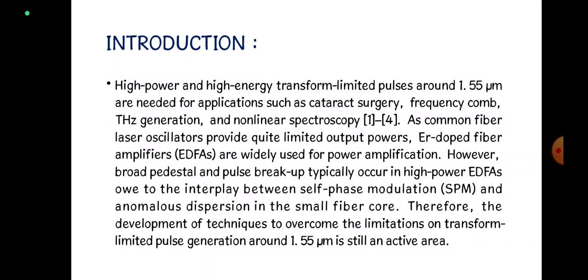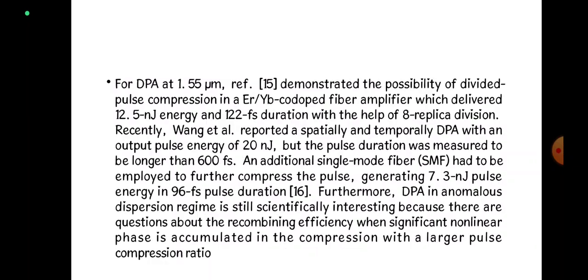However, broad pedestals and pulse breakup typically occur at high power, due to the interplay between self-phase modulation and anomalous dispersion in the small fiber core. Therefore, the development of techniques to overcome the limitations on transform limited pulse generation around 1.55 micron is still an active area. For DPA at 1.55 micron